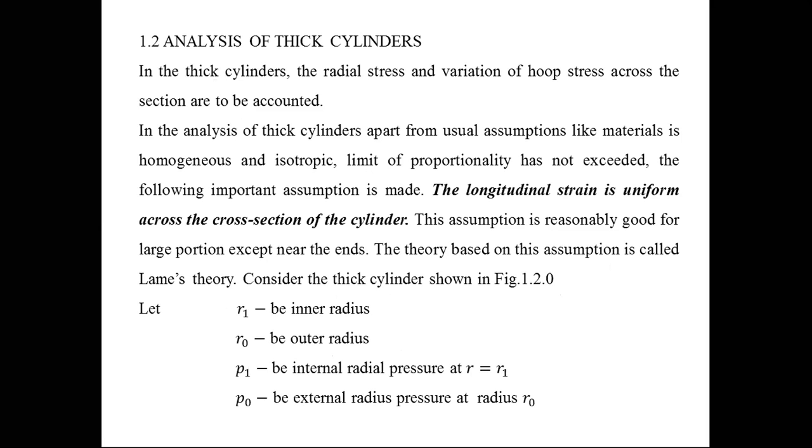Actually, it will not be uniform in thin cylinders also. Because the stress is not uniform, but varies from maximum at the inner side to minimum at the outer side. In thin cylinders, we start by assuming the circumferential stress is uniform throughout the cylinder, but you cannot accept it like that. The maximum is at the inner face and the minimum is at the outer face. So the variation may be looked upon as negligible, and the stress is sensibly uniform.